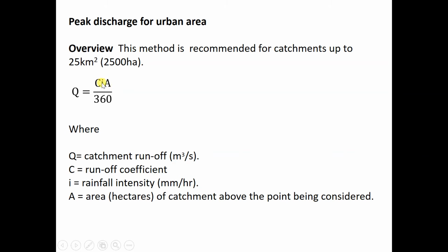Because usually the water, when it falls on the ground, will go into the roads. They got the catch pit, and from the catch pit they go into the stormwater pipe. Usually under the road or beside the road, they have these stormwater pipes. So all the water in the road reserve in the area, even the water from the roof, goes down the gutter, and eventually down to the stormwater pipe.